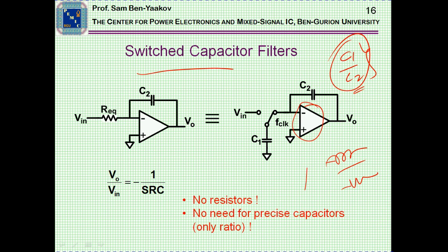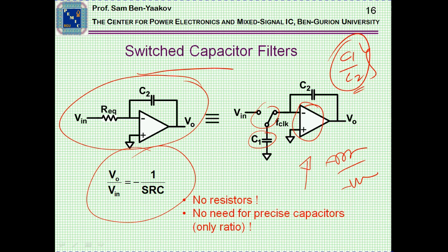So this switch capacitor circuit behaves like an integrator, and this will be the transfer function, and this will be the basic building block of the active filter in the differential equation approach. Now what we have here is a capacitor plus a switch, which is sort of connecting the capacitor to the input and then to the virtual ground. Here is virtual ground, that is, the voltage here is zero due to the feedback through this path.